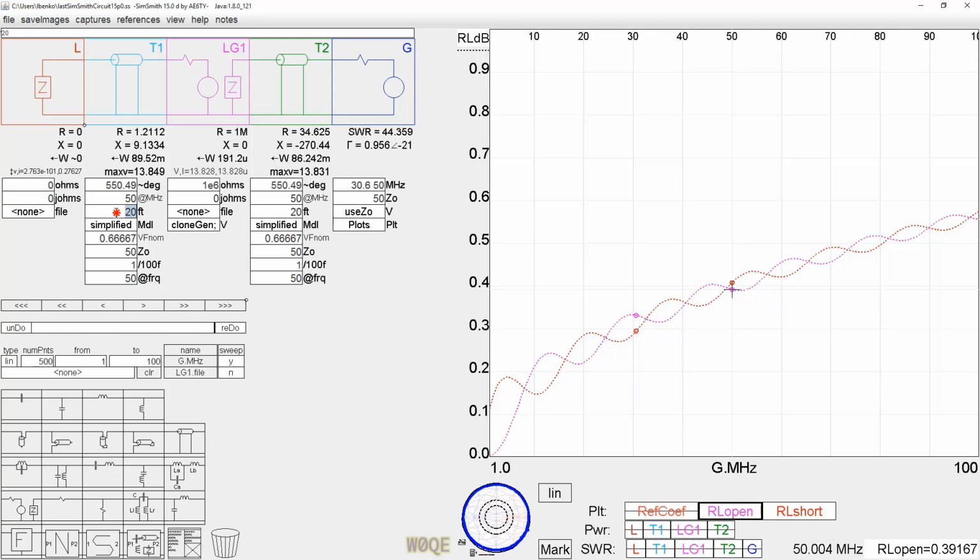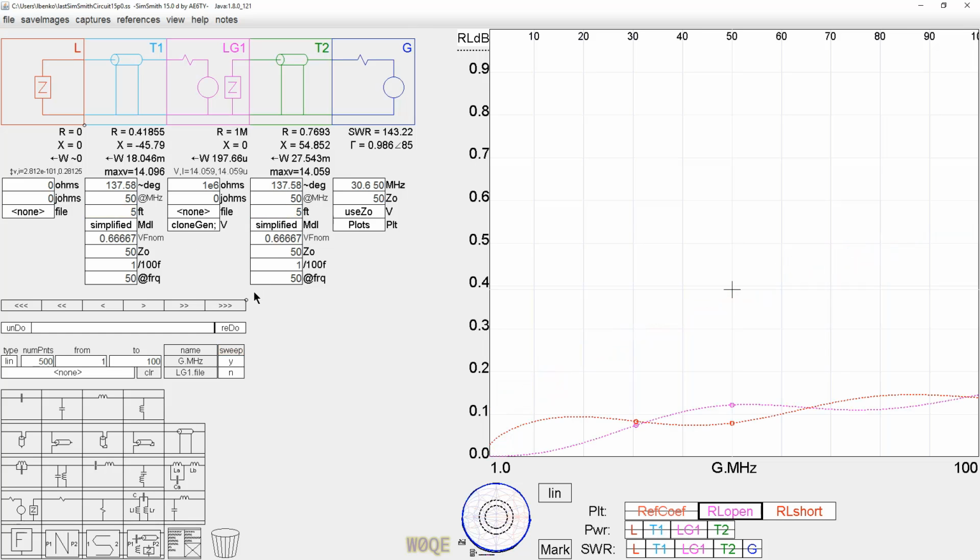or if we were to shorten the length of the coax to be like 5 feet, say, it's a little harder to measure because the loss is less. The loss would now be 1/20th of a dB out and 1/20th of a dB back, which would be 1/10 of a dB. And we can see it's roughly a tenth here, but the two numbers that we're averaging are a little bit further on either side.